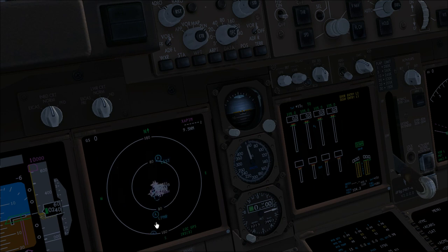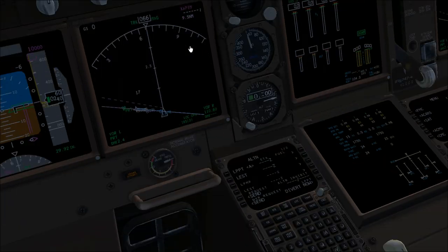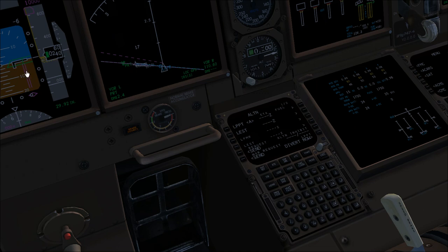If you can actually zoom out, you can see those alternate airports being indicated with a blue circle and an A in the middle. We can now return to 5 and get to the map. If you can see, we have just selected an approach. We are in the same airport of the approach, so we have the localizer aligned, and if you can see, the updating of the position of the IRS is both IRS 3, so 3 platform, GPS and localizer, because we have the localizer too. We go to the route page, and we go to the performance initialization page.